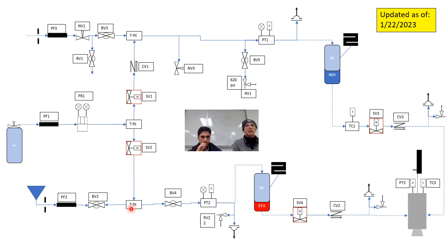Ideally, some kind of automated test that can go through all of that as a backup to manually checking every single valve and instrument. Then we can power off the system. And we really want to make sure that this system is purged before we do anything. So nitrous oxide, the bottle should not be connected. Ethanol, the bottle, nothing should be in there. This system should be purged. It should just have atmosphere in it at worst.